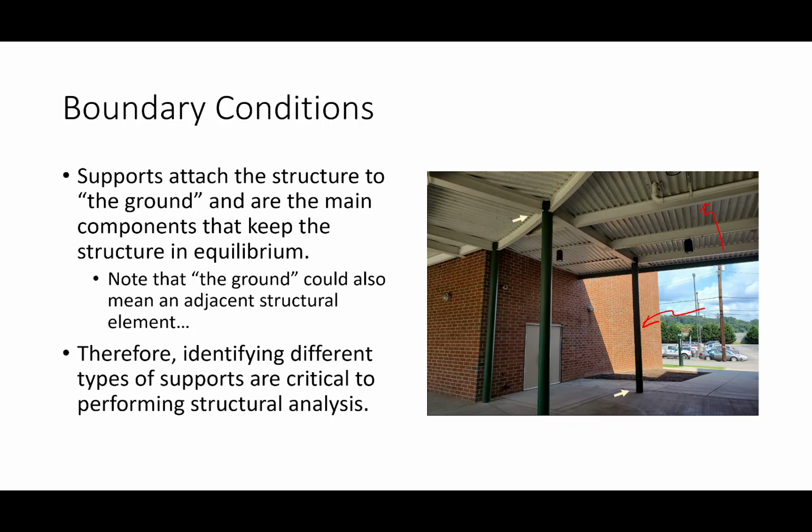In other words, if I'm looking at this column, let's say I'm looking at this boundary condition right here, this place where the column is connected to the ground. Is that connected in such a fashion that we would consider that a fixed boundary condition? Would we consider it a pinned boundary condition? Or maybe more specifically, what's the difference between a fixed boundary condition and a pinned boundary condition?